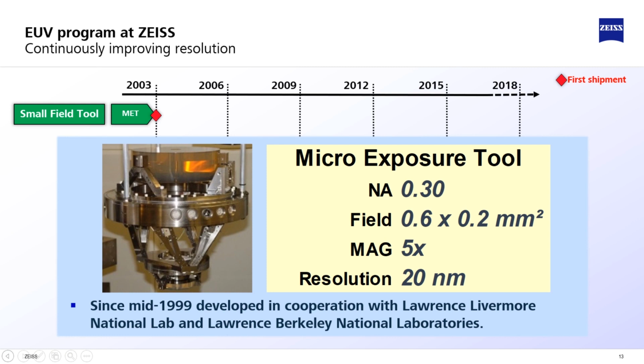The system consists of 2 mirrors based on the concept of nearly equal radii of curvature. The optics features a central obscuration. A small hole can be seen in the top mirror. By applying surface interferometry and polishing with a repeatability of 60 picometers, mirror figure and roughness values from 0.2 to 0.3 nanometers were achieved end of 2000.